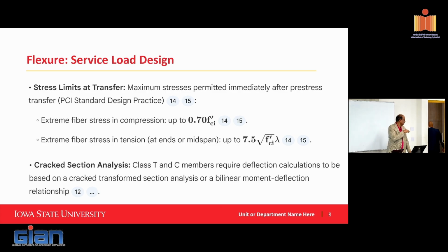Why is it reduced? Typically the reduction is given for two reasons. One is obviously you don't want to go past the elastic limit, right? Concrete behavior does not remain elastic all the way to the peak. The other thing is that you don't want to put too much stress in early on because the creep will be significant. That's why they limit how much stress to put in.